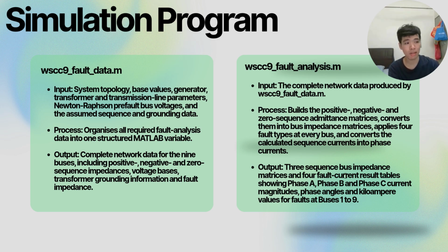After getting all of the data, this program will organize them into one structured MATLAB variable and then output them as complete data of the nine buses, including the positive, negative, and zero sequence impedance, the bus voltages, the transformer grounding information, and the fault impedance. So basically, it just processes the data into a more structured format, and then all this data is fed into the second file, which is the fault analysis.